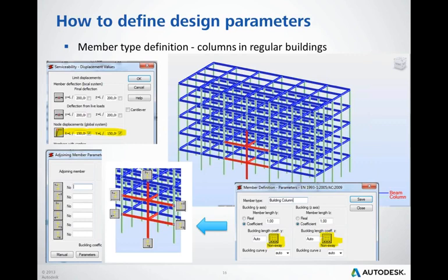That's why I said you may just make a small model and then compare. You can compare the automatic detection of buckling elements, with the automatically calculated buckling coefficient, with the one that you obtain by indicating the adjoining elements manually.